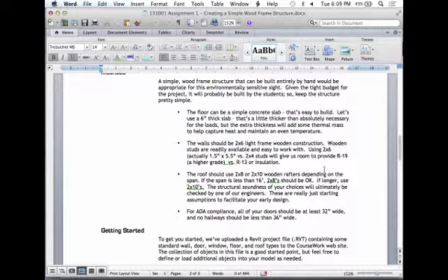Then we have some sort of roof on the structure, and depending on how a roof works, we might have it singly sloped or doubly sloped. Just based on the size of this building, if this distance across here is, let's say, 16 feet or less, you'll probably have a very simple structural system where it'll just be these members that cut across that I'll call rafters, which are kind of like studs of walls, but they'll cut across like this.